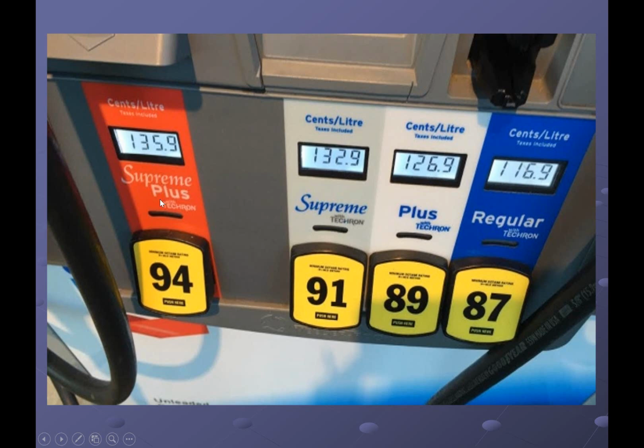Note, although let's say a 94 octane number we're going to see is a better quality fuel, not all cars are engineered to run off the high quality fuels. So basically when you buy a car, if you read the manual, it'll tell you what specifications your engine was designed for. Basically put in the fuel that your engine was designed for. You could risk damaging your engine if you put fuel that's too high quality or too low quality, because your engine may not be designed for that specification.